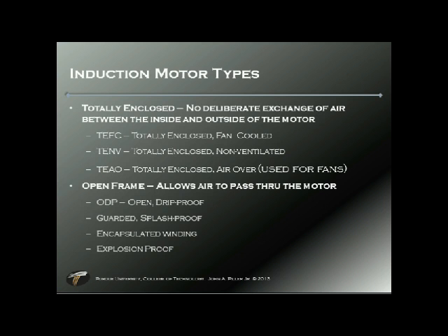Okay, so induction motors have different types for different purposes. This is mechanically what it looks like. The case that the motor is in is what we're going to describe here. We have basically totally enclosed and open frame. Totally enclosed allows no deliberate exchange of air between the inside and the outside of the motor. Open frame allows air to pass through the motor.